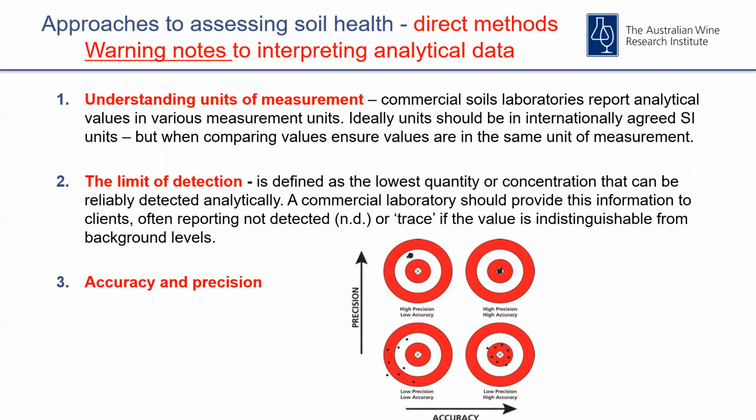if you were to send the same soil sample to the same lab 10 times, you get an idea of where this is sitting in terms of that sort of stuff. A range of different methods have quite varying levels of accuracy and precision. So it's important to understand that, and it has implications for the repeatability of the measures you're looking to take.